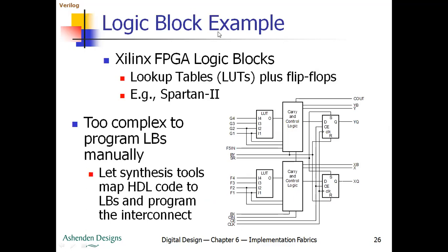Now, here is a logical block example. We have a simple diagram to represent the logical block in the case of a Xilinx FPGA. Xilinx is the main vendor or supplier of these FPGA boards. This example belongs to the Xilinx FPGA Spartan 2 family. You can see that this logical block is divided into slices, where each slice is again divided into two parts.